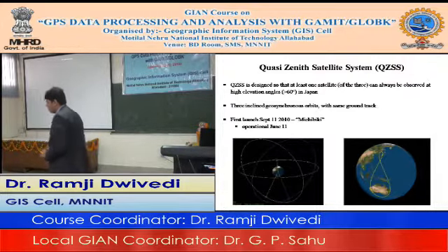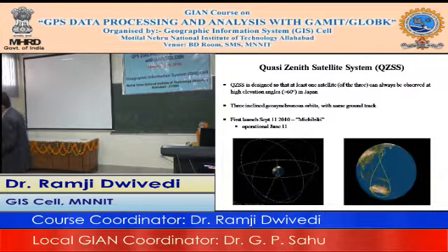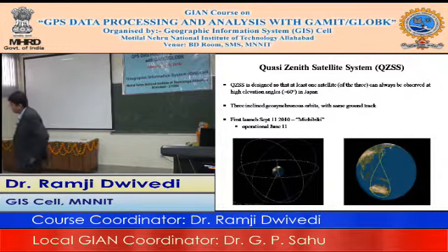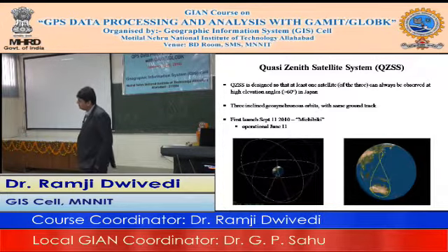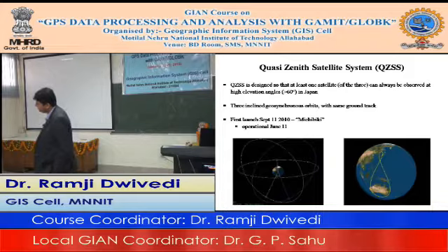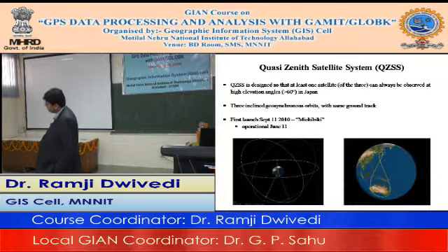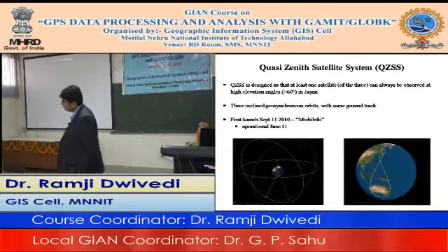Both can be followed, I think. Yeah, I think with all these names for these kinematic systems, they sort of evolved with time, and to a large degree they've lost a lot of their meaning. The biggest one originally was that in the first kinematic surveys that were done, you had to maintain lock on the satellite, and if you lost lock, you would have to go back to a previous occupation to reacquire it. And then the idea of using the pseudo range and the phase to be able to resolve the ambiguities without having to maintain lock, that led to all of these.